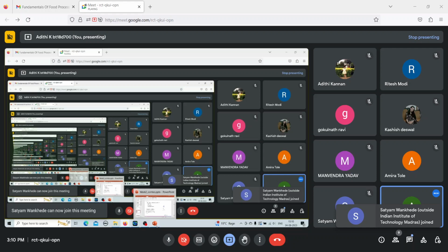So now the Kelvin model and the Maxwell model. I'm basically repeating what I said here. Elastic and viscous components are represented by spring and dashpot respectively. The Maxwell model is used to interpret the stress relaxation of viscoelastic liquids, especially polymeric liquids. It was initially developed to describe polymeric liquids, and in this case your two elements, the spring and the dashpot, are connected in series, and the total shear strain can be expressed as the summation of strain in the spring and the dashpot.